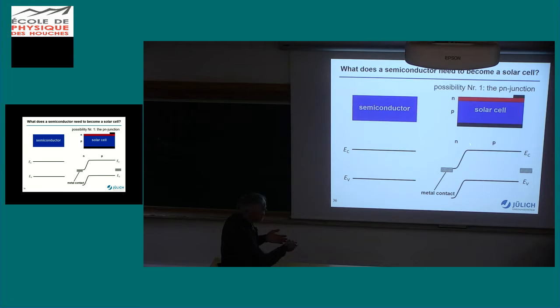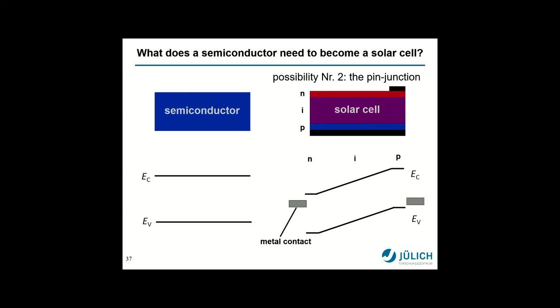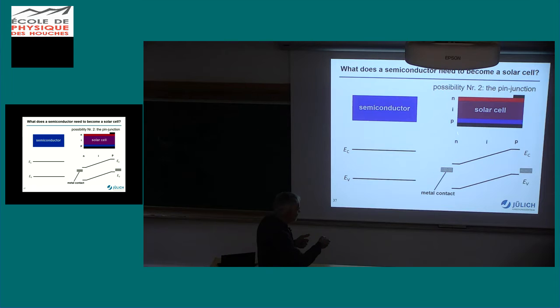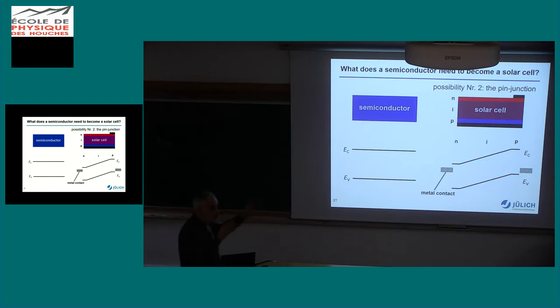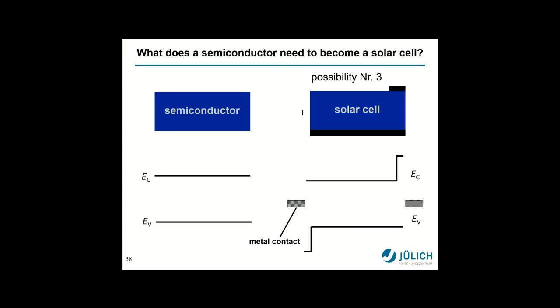It's just by packing something that is not doped, not charged and not chargeable or almost not chargeable, in between the N and the P, and that gives you this NIP structure. There's a doped region, another doped region, and that region is undoped, and then you stretch this space charge region almost all over the entire device.